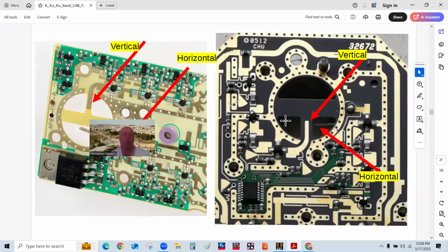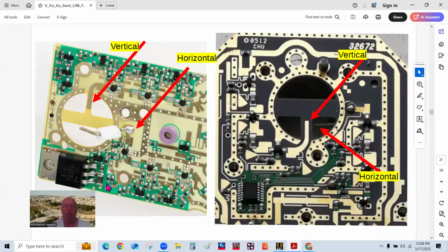So let's look at some of these and I'll explain them in correspondence to the model that I did in ANSYS. So we've got a printed probe in here that goes into a three-stage LNA in here, you can see. And then I've got another one, which is this guy here. Okay, now there is a lid that covers this. That lid here becomes the back short for this.